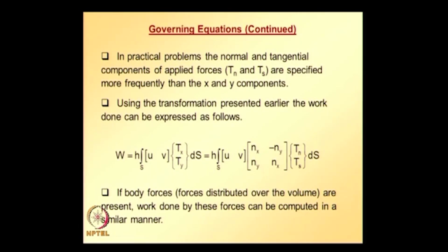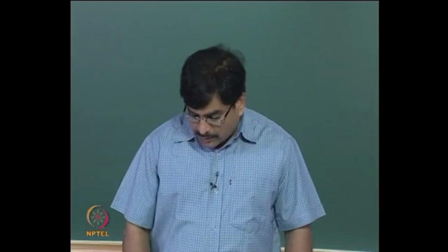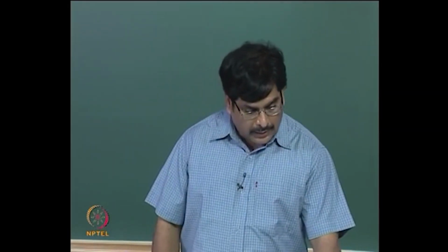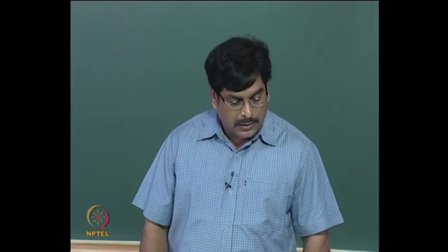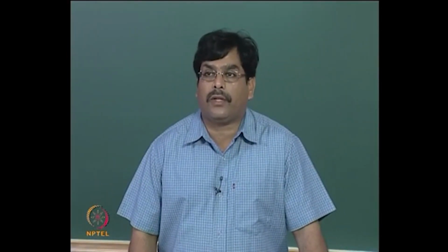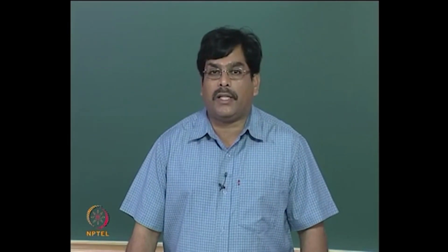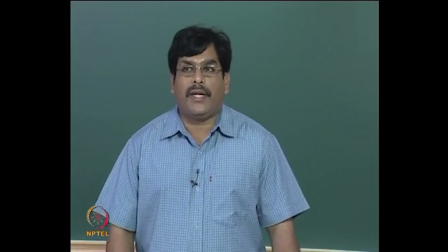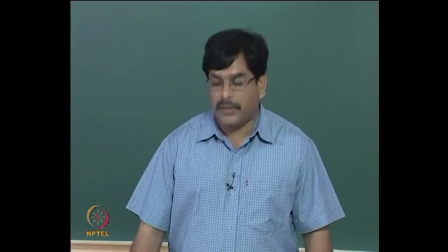So, now we need to verify whether the functional that is given, that is strain energy minus work done by the applied forces, is the correct functional for the 2-dimensional elastic problem or not. To verify that the potential energy functional is appropriate for plane stress and plane strain problems, we must show that the governing differential equations are recovered by setting the variation of Pi p equal to 0.